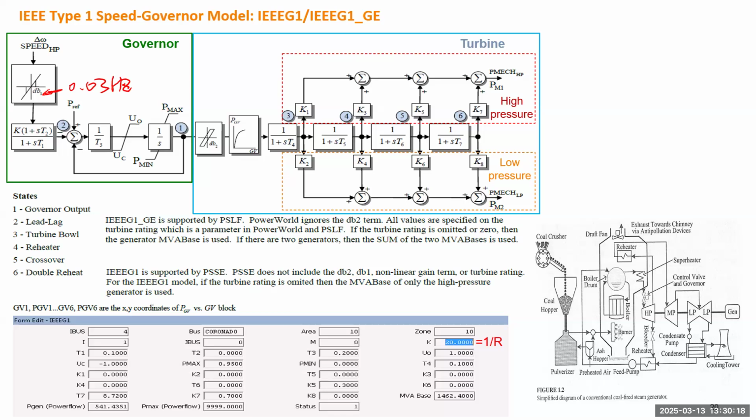All right, next the signal goes through this component, which has some time constant. That time constant together with this time constant, T1 plus T3, will be roughly the time constant for the governor, the tau g we used in the earlier slide. Everything starting from here belongs to the turbine. We translate the valve opening into the mechanical power change.